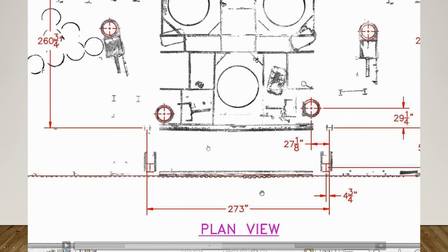Often I do this in Class 1 Div 2 areas or Class 1 Div 1 areas where I take the laser scanner in and scan. The equipment is not Class 1 Div 1 rated. Typically, there is one you can get, but it costs a lot more, and it's bulky and hard to use. But you can often use a sniffer and just measure the level of explosive material in the air, and most companies will let you go ahead and take the laser scans.